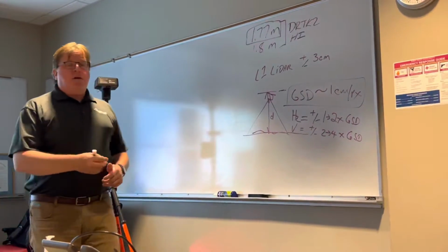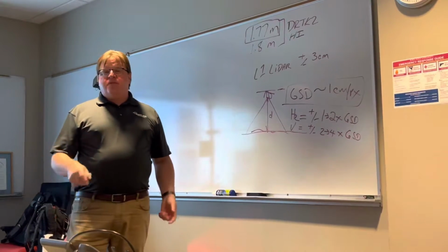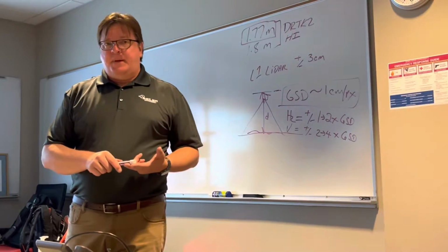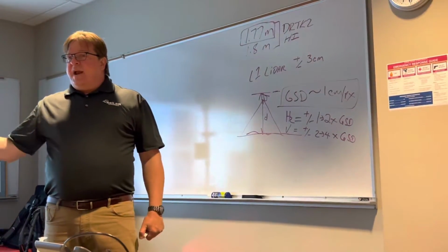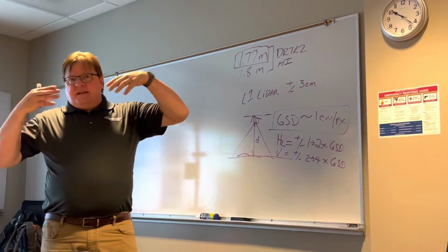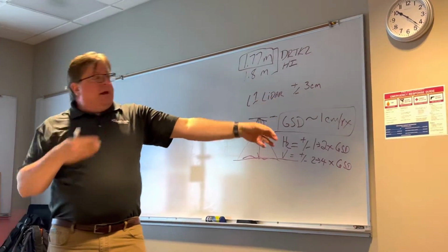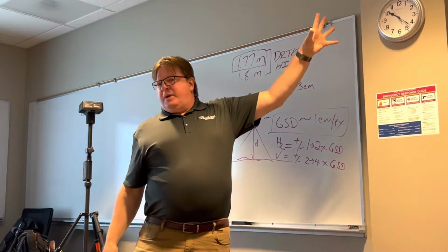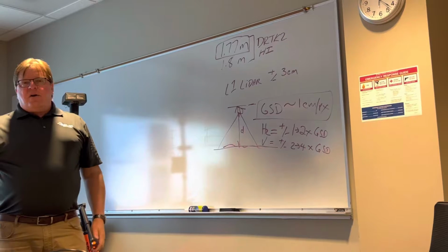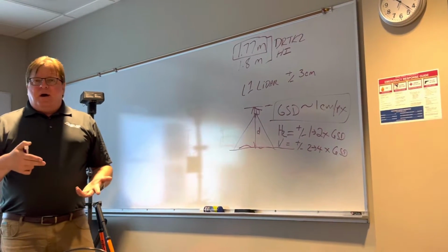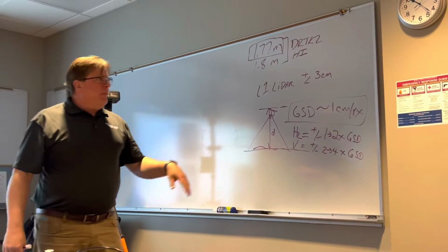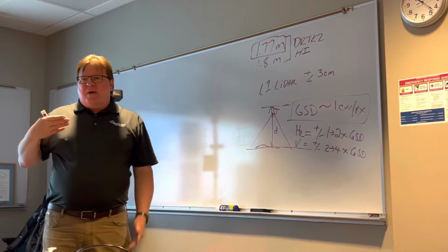It's shooting out. So LiDAR is shooting out. This particular LiDAR shoots anywhere from 168,000 to 240,000 active LiDAR points per second. Okay, so it's broadcasting and spraying laser light out. As it bounces off an object, returns and calculates the time for that phase length and says, okay, it's X feet away. As I start building up this point cloud of active light points, it's starting to build the picture. Okay, the only thing that affects LiDAR are things like atmospherics and medium. There's a bunch of stuff that affects the speed of light and through medium, blah blah blah. But at the altitudes we fly, we only fly within 200 to 400 feet.